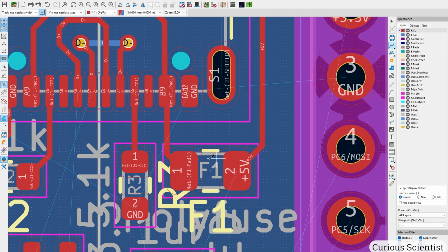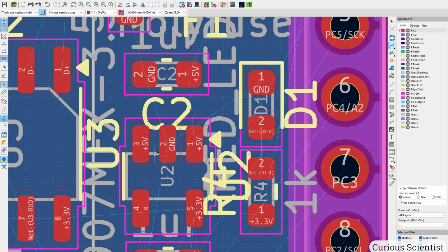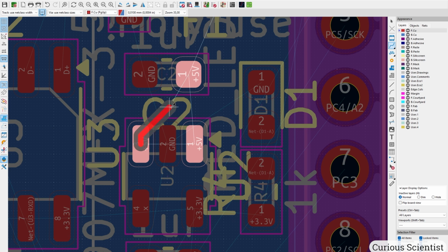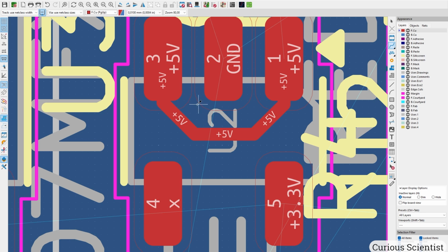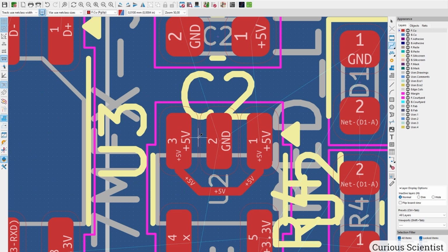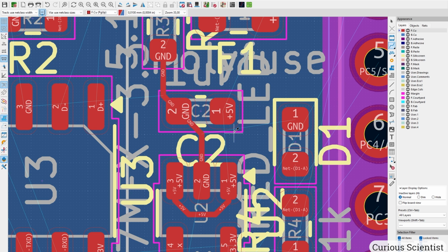So this is done. And then we can see that we have a bunch of ground here. So maybe instead of connecting these two like this, I can route under the chip, because this is nothing that the load goes through or anything, it's just the enable signal. And then all these 3 grounds can be connected together here. So maybe I can even make an island.